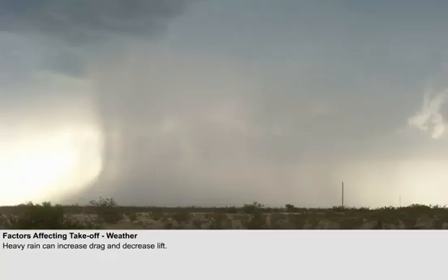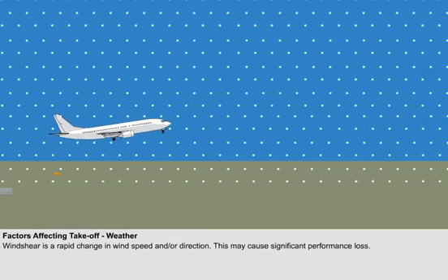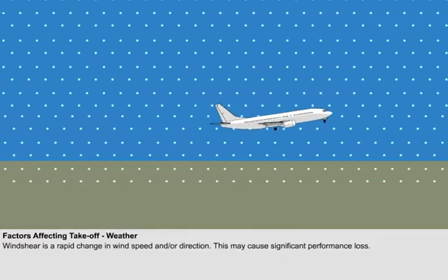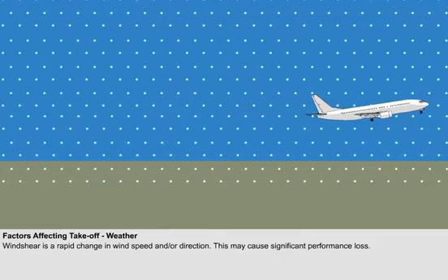Heavy rain is usually accompanied by other potentially fatal hazards. These include decreased visibility, wind shear, and microbursts. Wind shear occurs when there is a rapid change in wind speed and direction. If this occurs when the aeroplane is at or near the ground with low forward speed, then there is a considerable chance that the aeroplane will become uncontrollable and may even stall. Takeoff, when wind shear is observed or forecast, should be avoided.